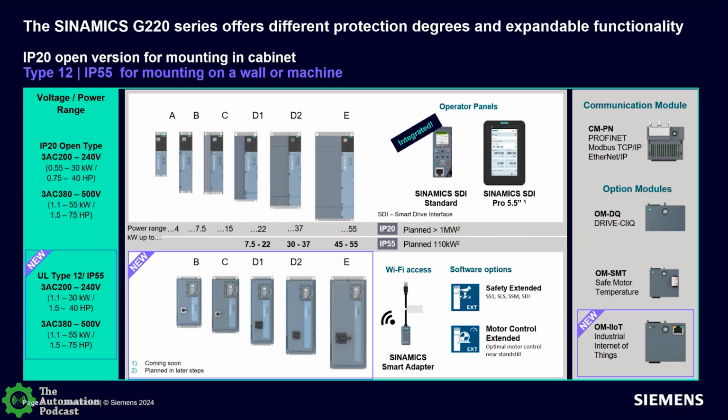And some good applications of that, Shawn, I think are, okay, maybe where someone was using a across-the-line starter, maybe on a ventilating fan out on a factory or something like that, and I want to use a VFD today. Okay, I can mount this product out on the wall and don't need its own control cabinet.